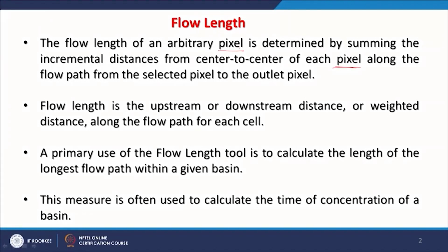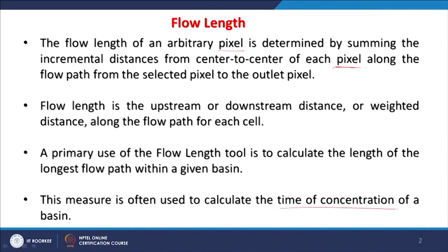We can determine that through this step in surface hydrologic modeling. Flow length is often used to calculate the time of concentration of a basin, which is directly linked with flood forecasting. It may also be related to sediment flow or other pollutants, because after all, time of concentration is how much time it would take to reach a particular location.